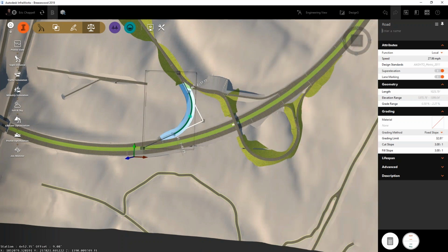We had a question come in while you were showing the quantities that I actually didn't know the answer to. Do you know if it's possible to view the quantities for all of the component roads in your model? Yeah, you just have to select them all. Great, that was so simple. I don't know if it's possible to select them all in Model Explorer, but typically you don't have hundreds of them, so it would probably be easier to just hold the control key down and do multi-select, or you've got a number of selection tools, like select by window. And that was actually a follow-up question. I think you may be able to right-click on a feature class in Model Explorer and do a select all, or view in data table and select from there. Yep. Great.